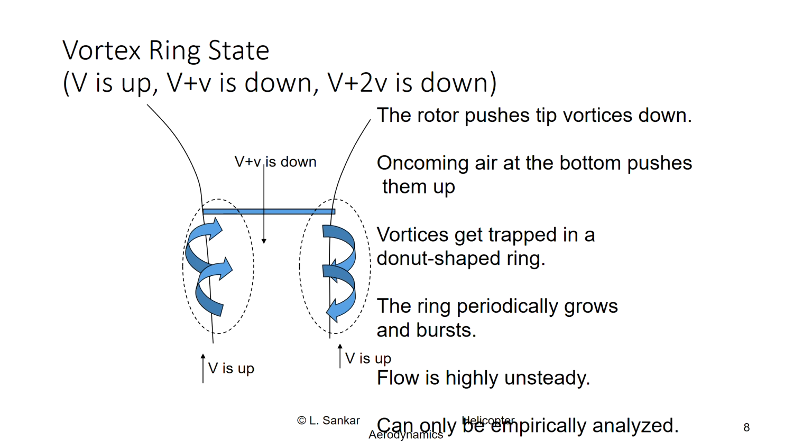Now, what happens in the wake case? Remember in our previous discussions on the vortex wake-based inflow model, we said a helical vortex structure forms underneath the rotor. The helical vortex structure is also contracting, so it's descending, it's contracting. So it wants to be pushed downwards by this quantity v plus capital V, but the upward directed velocity is pushing it upwards.